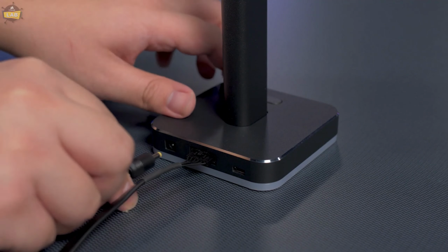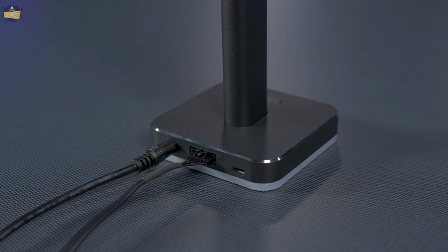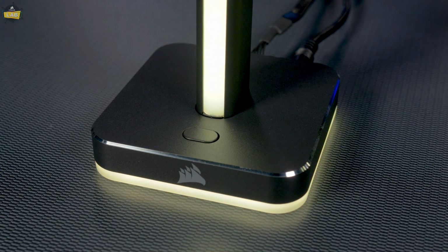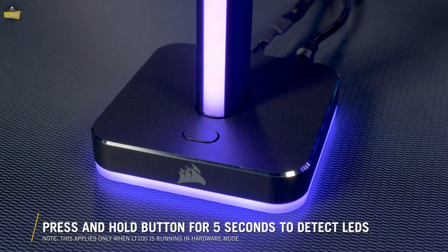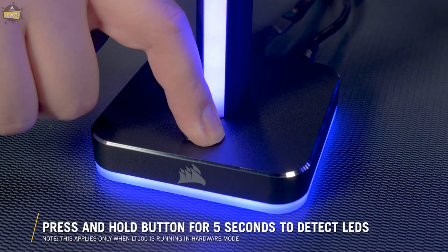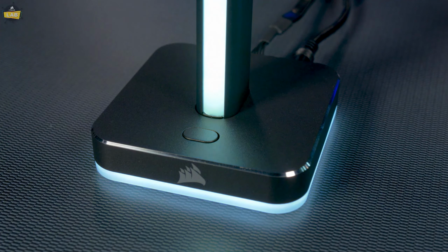Connect the power cord to the base of your main lighting tower and connect the other end to an open electrical outlet. The LT100 starter kit can operate without software using the multifunction button on the main lighting tower. If you've added additional towers through the LT100 expansion kit, you'll first want to press and hold the multifunction button for 5 seconds to ensure that each tower is detected by the lighting controller.